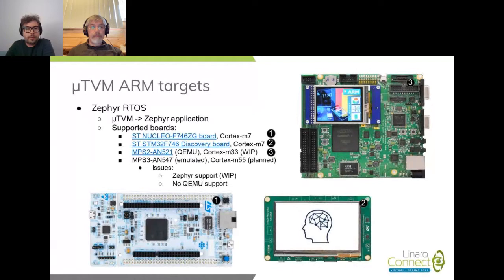So we've been working since the beginning of this year with a couple of ARM targets, and experimenting with µTVM on top of those targets using primarily Zephyr RTOS. And from Zephyr's perspective, µTVM is just an application for Zephyr. And in doing that, we have successfully run µTVM on Nucleo boards, which have a Cortex-M7 based MCU.